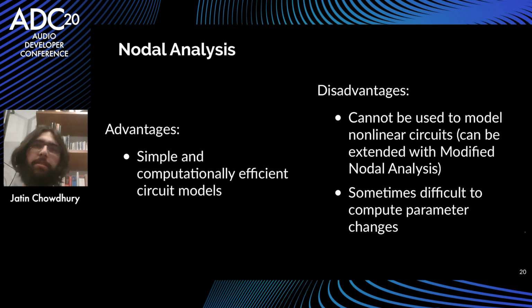So just real quick, some advantages and disadvantages of using nodal analysis. It's pretty simple and it's pretty computationally efficient once you get your digital model made. Most of the other circuit modeling methods that I'll be talking about after this are not quite as efficient as nodal analysis in real-time implementations. So that's definitely an advantage of nodal analysis.